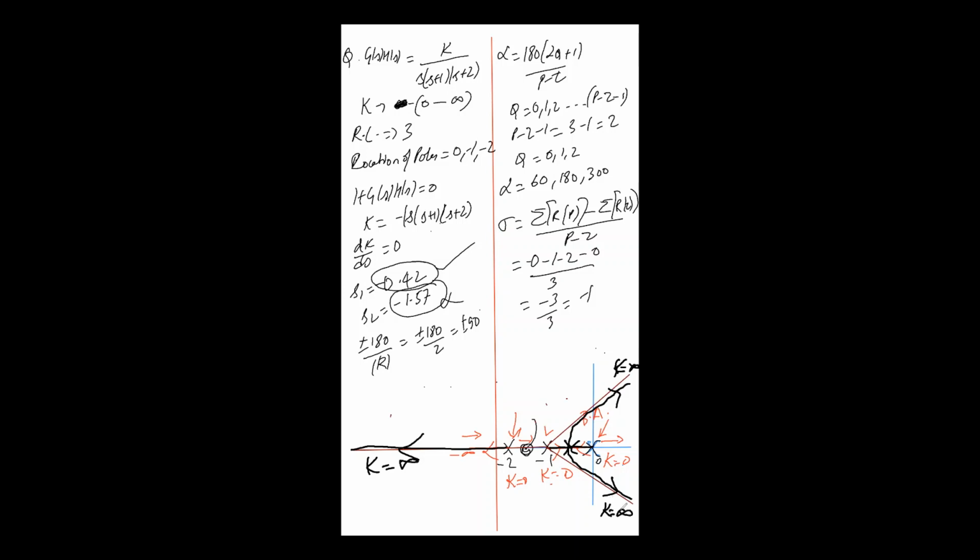Right? So this is the complete root locus we have drawn, but still there are some parts which we can calculate. So we will see what those parts are. Now, if you want to calculate this part where your root locus is crossing your j omega or imaginary axis, how to calculate that? I've told you that you calculate that by using the Routh-Hurwitz criteria. So this is your characteristic equation. You have to build a Routh-Hurwitz table for this. Keep your notes by your side. I will just erase the whole page and let you know how it is done.